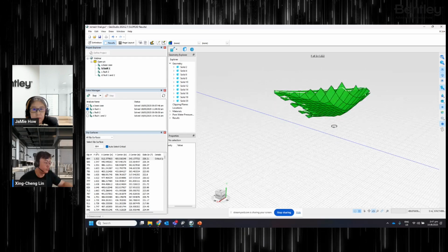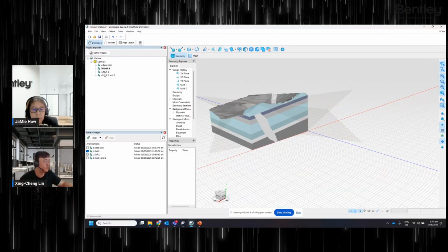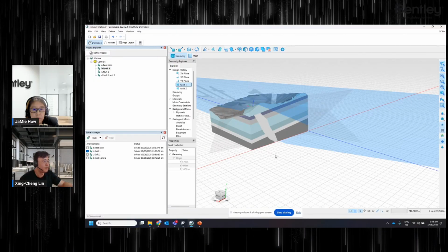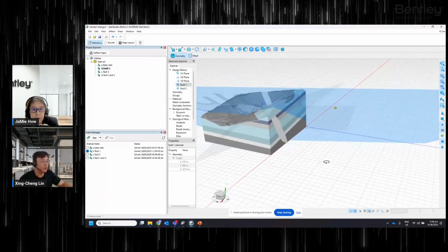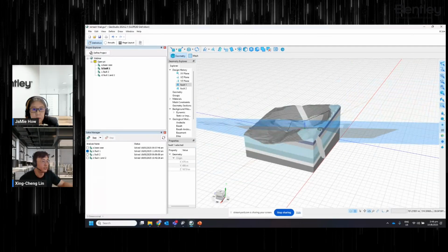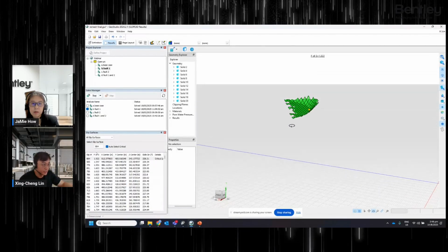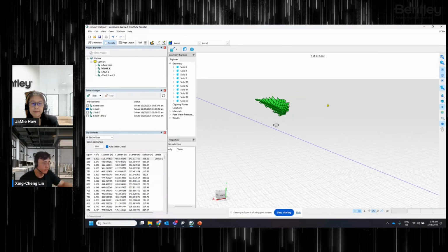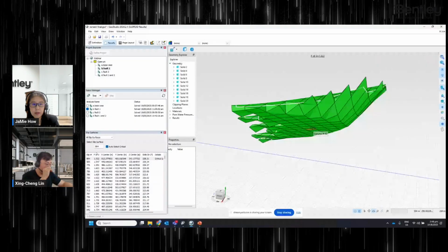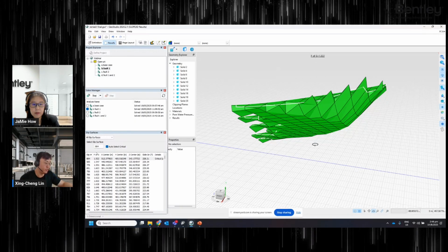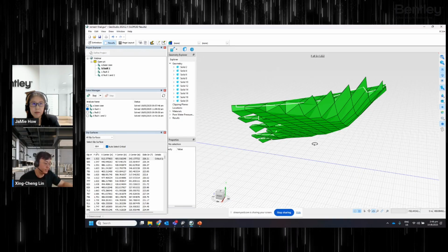So we see fault one is dominant on this portion of the open pit. If we go back to the define, fault number one is here. This is how it actually intersects with the geological volumes. So it actually sets the tone of how our critical sliding mass is going to be like. It's a planar translational slide over here, so it's not surprising that it imposes an effect on the shape. No longer do we see this kind of ellipsoid, but rather translational planar failure surfaces.